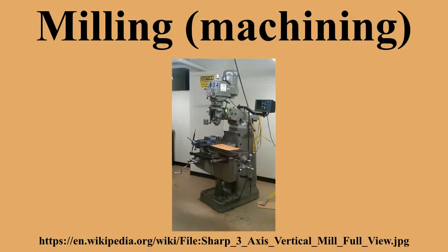Horizontal mill. The horizontal mill has the same sort of setup, but the cutters are mounted on a horizontal arbor across the table. Many horizontal mills also feature a built-in rotary table that allows milling at various angles. This feature is called the universal table.